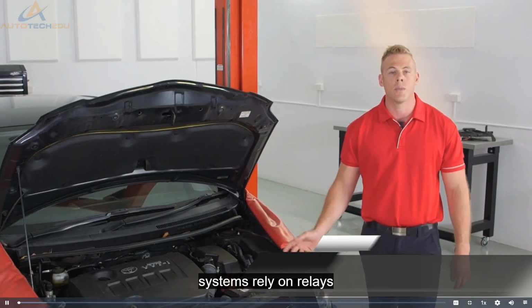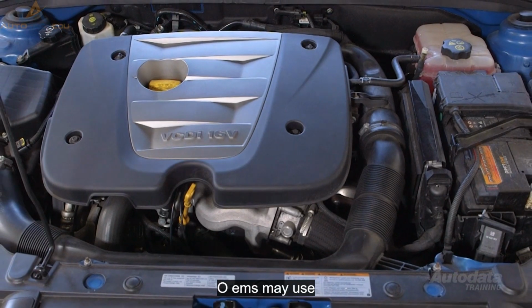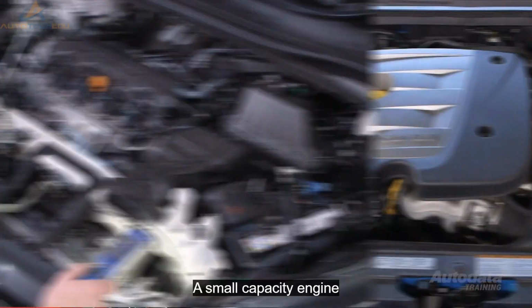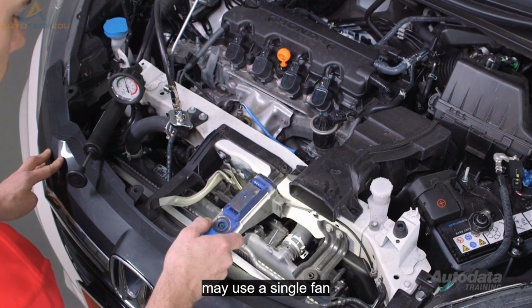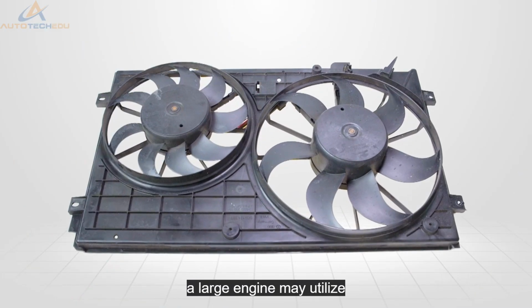Older style cooling systems rely on relays for switching individual fans on or off. However, this can get confusing when multiple relays are used for variable speed activation. OEMs may use different fan configurations depending on the size of the engine. A small capacity engine may use a single fan with 2 speeds, whereas a large engine may utilise dual fans